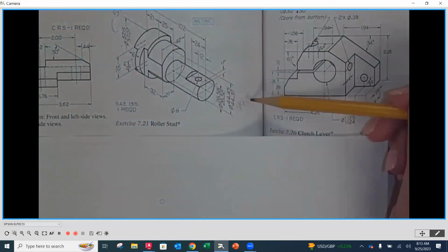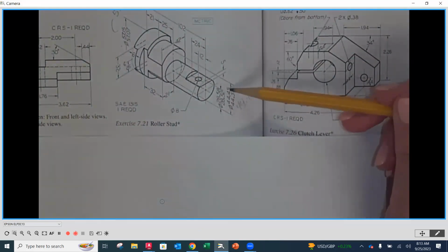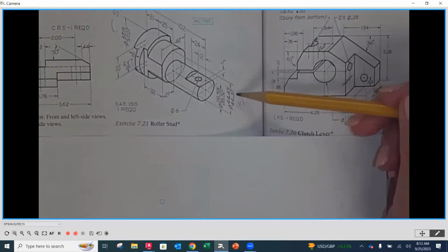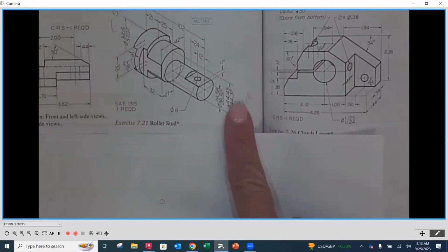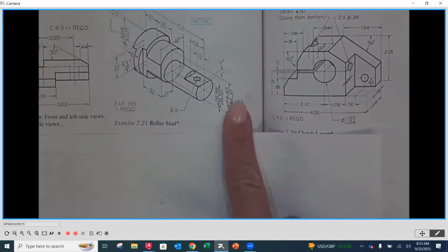Okay, so when I look here, you'll notice if 44.41 is the middle, I would add 0.04 to get the top number, and subtract 0.04 to get the bottom number again. So that's good. These two can use the same style. They're two place decimals, and they're both plus or minus 0.04. So you'll set up a style that's going to reflect that.